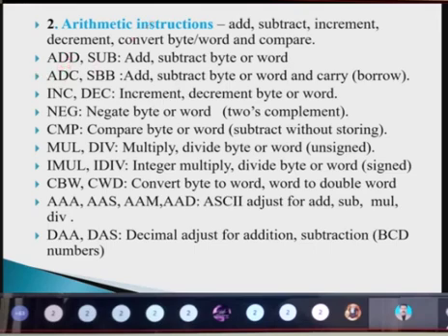For example, ADD and SUB. If I want to add any two values present in the registers, normally we will be using capital letters only for the instructions. So if I'm giving ADD R1 comma R2, both the values will be added and that will be stored in R1. So to the destination register it will be stored. So that is the meaning of this ADD.